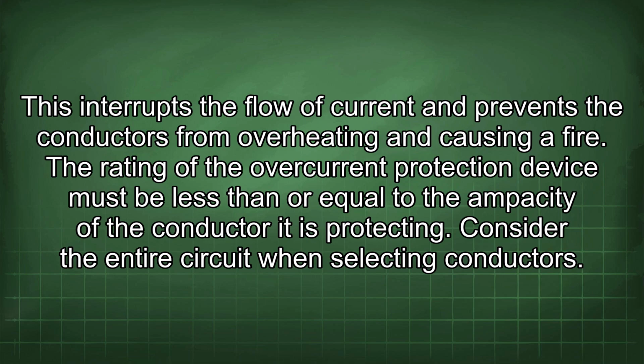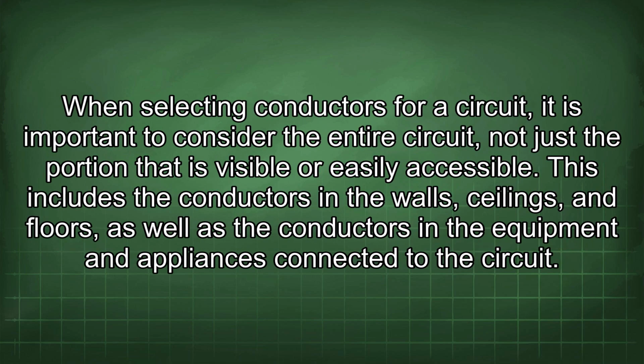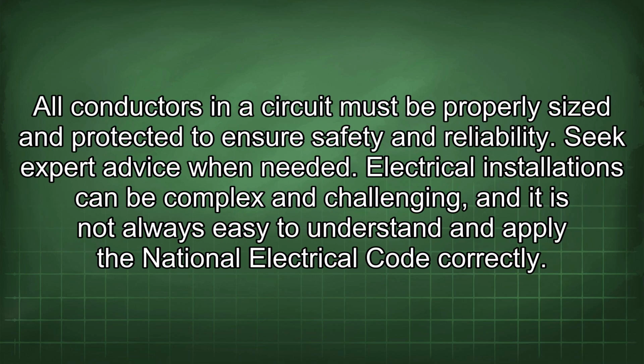is protecting. Consider the entire circuit when selecting conductors. When selecting conductors for a circuit, it is important to consider the entire circuit, not just the portion that is visible or easily accessible. This includes the conductors in the walls, ceilings, and floors, as well as the conductors in the equipment and appliances connected to the circuit. All conductors in a circuit must be properly sized and protected to ensure safety and reliability.